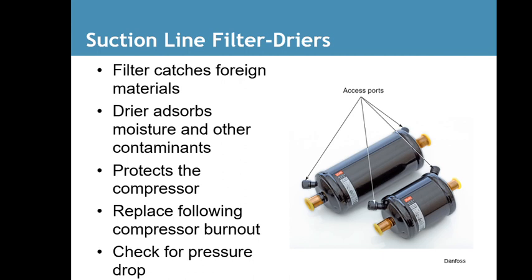Normally, when you have a burnout, you put it in for about a month and then go back out and take it out of the loop. It is a lot more work, and unfortunately you're going to have to pump down the refrigerant or reclaim the refrigerant to do this. But they clog very easily, and since the pressure is so much lower, it can cause a lot of problems with starving the compressor for refrigerant.